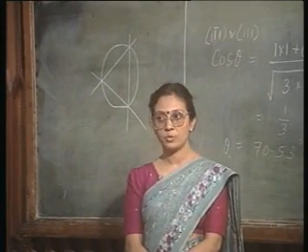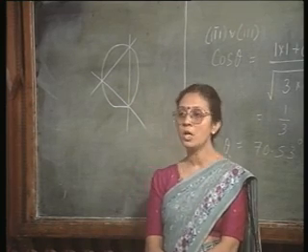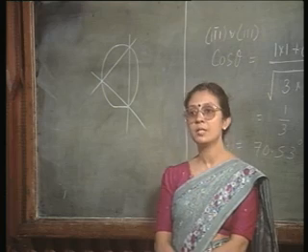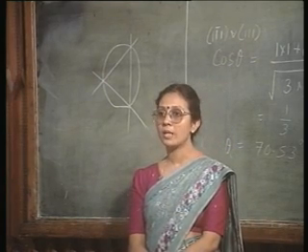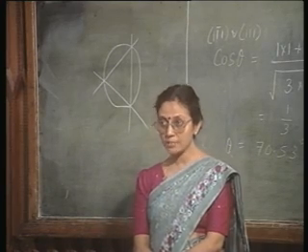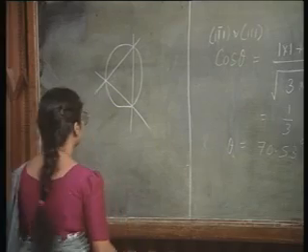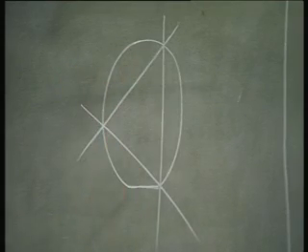So, you have a small problem here. What is that small problem? When I want to scribe silicon, I would like to get as many square or rectangular chips as possible. But in this particular case, you see, I cannot scribe in a mutually perpendicular direction.